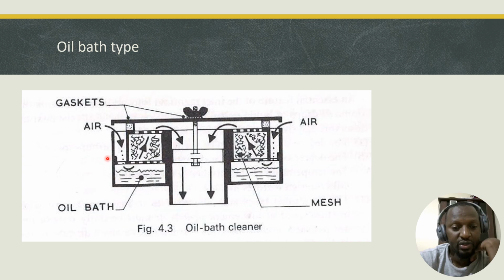You scrape them out, you clean the container, and then you fill it with fresh engine oil to the prescribed level, and you drip some oil onto the wire mesh, and you return the air cleaner. And if this air cleaner is maintained well, then it should last the whole life of the vehicle.